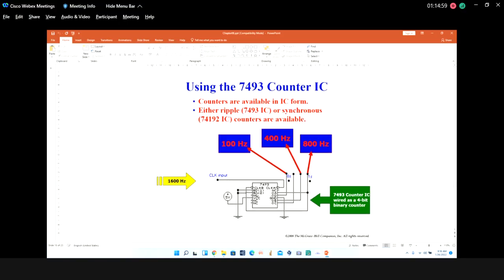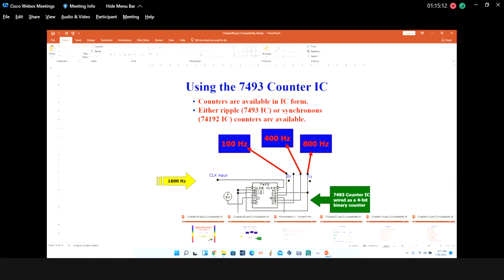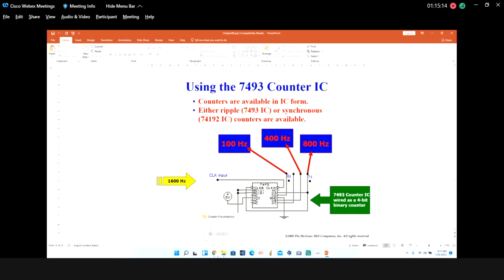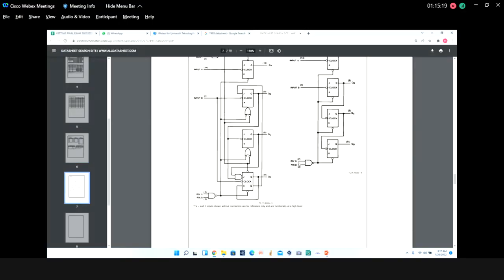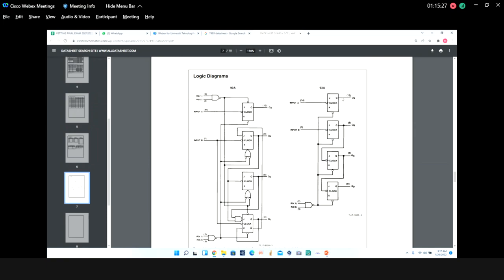And then in this case, why did they connect R0 1 and R0 2 to ground? Because they want to have a toggle function. Why toggle function? When this one is ground and then becomes high, it goes to all clear, and J preset is already set as high.